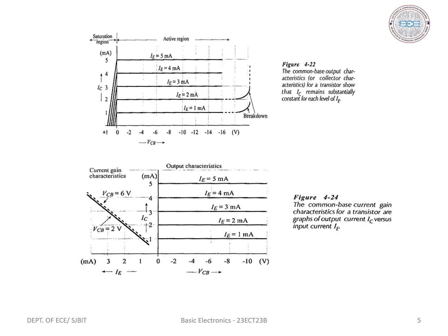Next, active region. In the active region, the emitter base junction is forward biased and the collector base junction is reverse biased. The collector current is constant and is equal to the emitter current. The dynamic output resistance of the transistor is defined as R0 equals delta VCB by delta IC. As the change in IC is very small in the active region, the dynamic resistance is large.